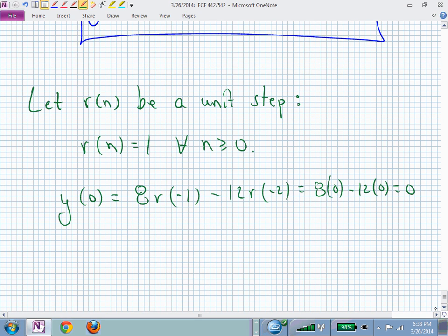We kick this with a 1 at 0, and what do we get out right then at the output? 0. Does that make sense based on your pole-zero excess? Your pole-zero excess was 1, wasn't it? So you better not see any response immediately when you hit it.